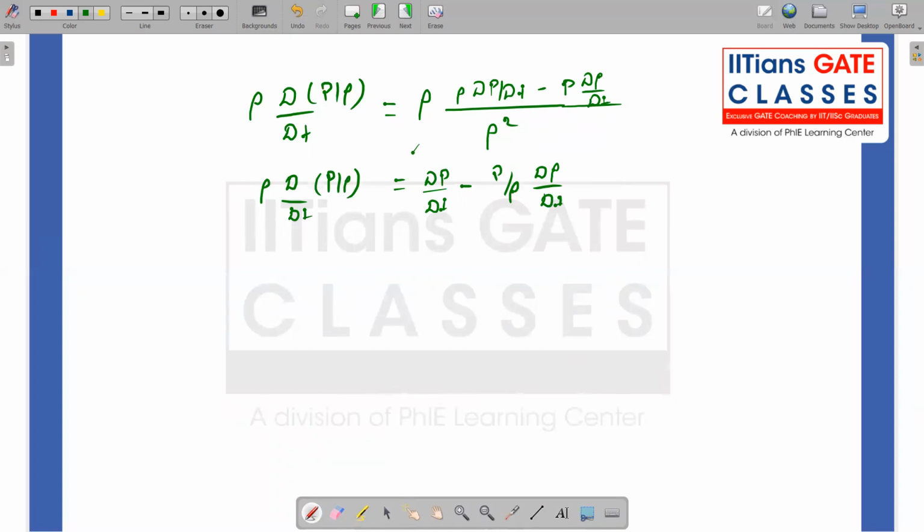So now I have the continuity equation. This gives me Dρ/Dt plus density field times divergence of velocity equal to 0. This is the continuity equation in the other form we discussed. So now I have Dρ/Dt in this equation, and I can substitute this Dρ/Dt here.